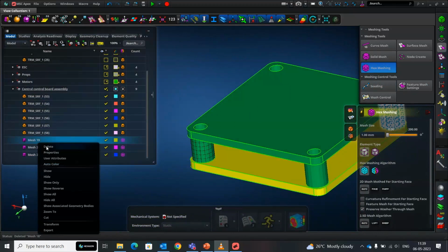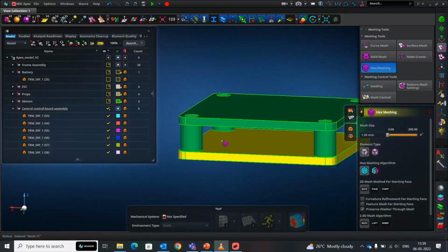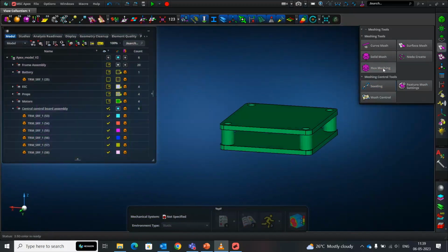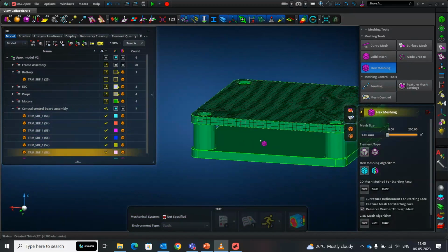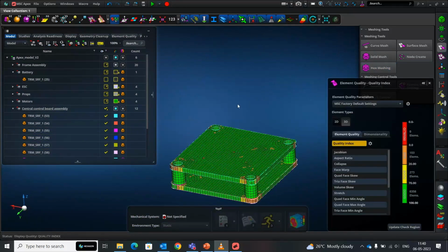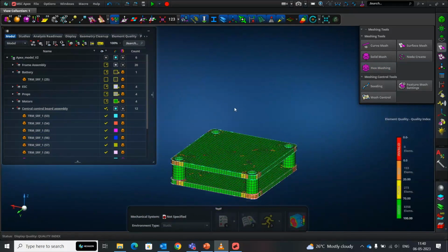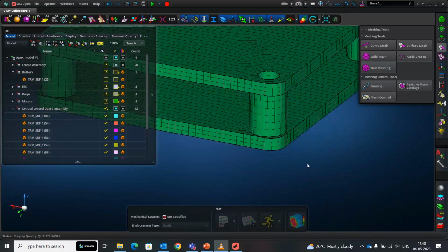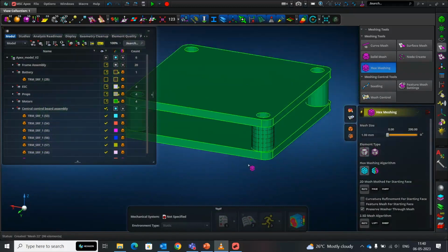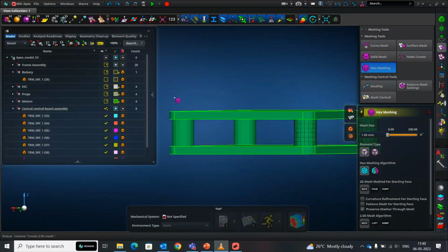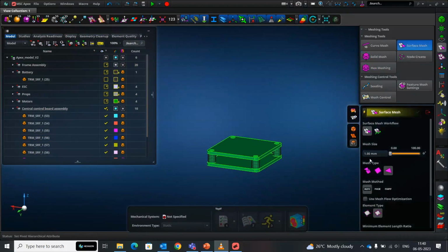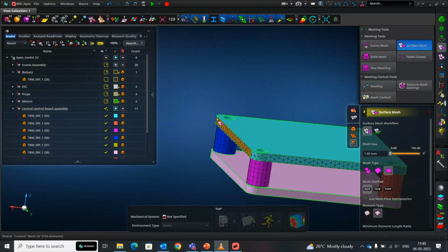So wherever it's yellow, it's saying that because of the mesh conformity, it's having some trouble recognizing the mesh, simply because it is not possible to be meshed, as there was some variation in the inputs that we had given. And now once we seed that appropriately, we can see that it is completely hex meshable again. So clearly this quality was struggling in terms of the hex mesh. So I'm going to delete this and just use hex mesh for the spacers because they are well conforming cylinders. And then for the upper and lower boards for the mount, I'm going to utilize the same approach that we've done before.